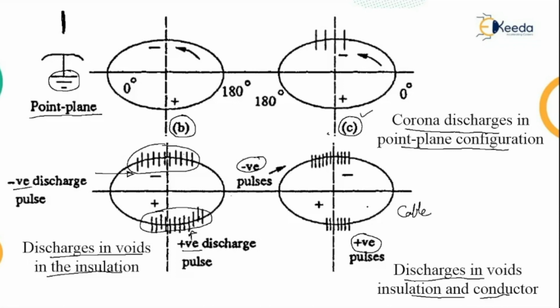With tuned narrow band detectors, the discharges can be detected with a sensitivity less than 1 picocoulomb for a test piece capacitance of 100 picofarad.